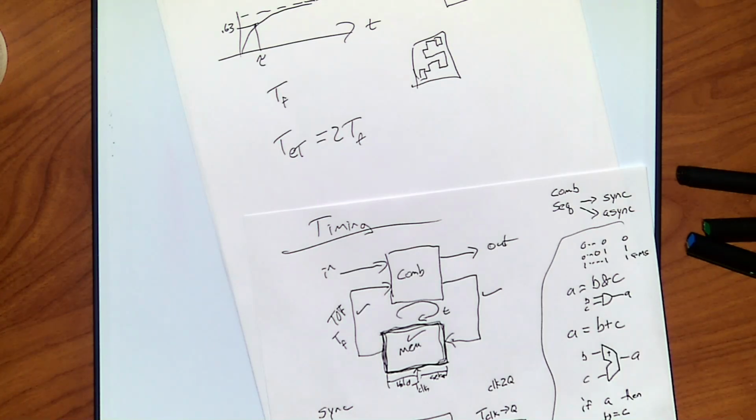So now if I've got a 64-bit number, you're talking 128 gates. That's how long it would take for the least significant bit to propagate to the most significant bit. Now, often many of your most significant bits are 0, right? Because 2 to the 64th is a stupidly large number, right? But technically speaking, it could happen.